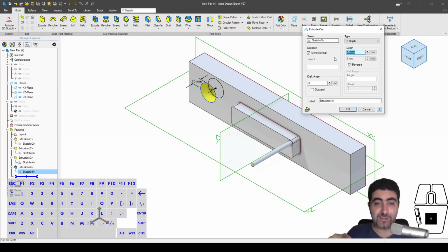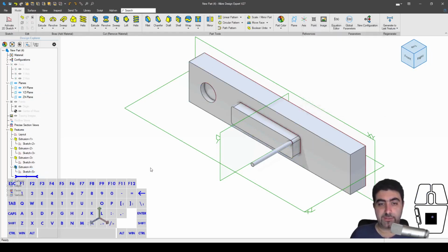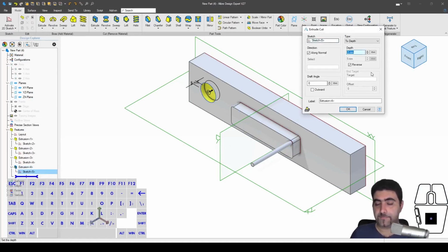Now, here's another tip from Ty, and I picked this up watching his qualifier video for the Spring Open, for Too Tall Toby's Spring Open. When an extrude menu pops up, the depth is highlighted, which is very useful because you can just say like -5, and you just created your extruded cut. But let's say that you do not want a specific depth.